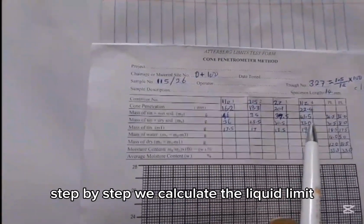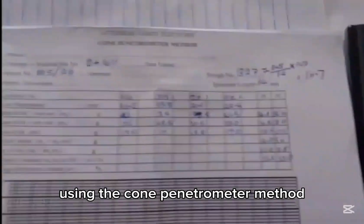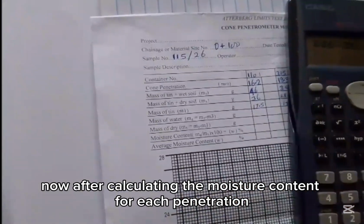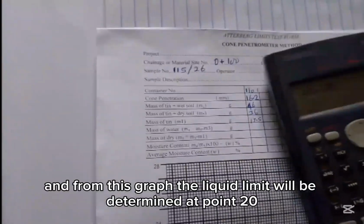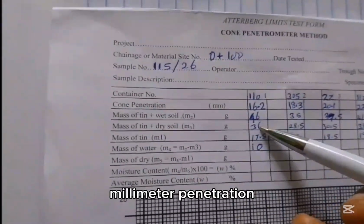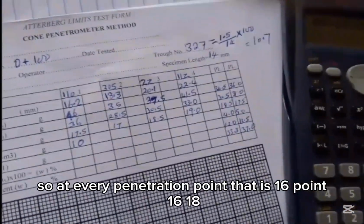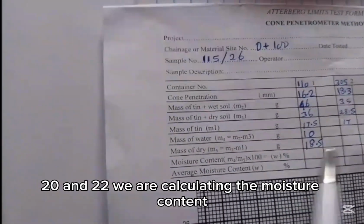We calculate the liquid limit by finding the moisture content at 4 penetration points using the Cone Penetrometer Method. Now, after calculating the moisture content for each penetration, a graph of moisture content against penetration will be plotted, and from this graph the liquid limit will be determined at 20 millimeter penetration. So at every penetration point, that is 16, 18, 20 and 22, we are calculating the moisture content.